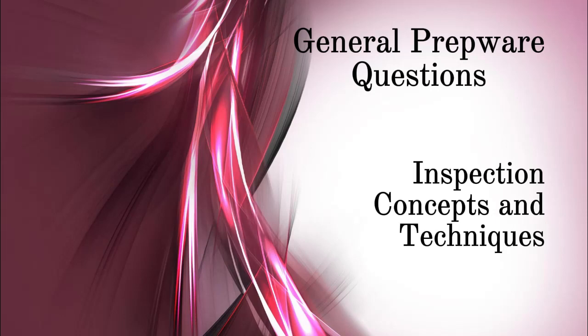What non-destructive testing method requires little or no part preparation, is used to detect surface or near-surface defects in most metals, and may also be used to separate metals or alloys into their heat-treated conditions? Eddy current inspection.